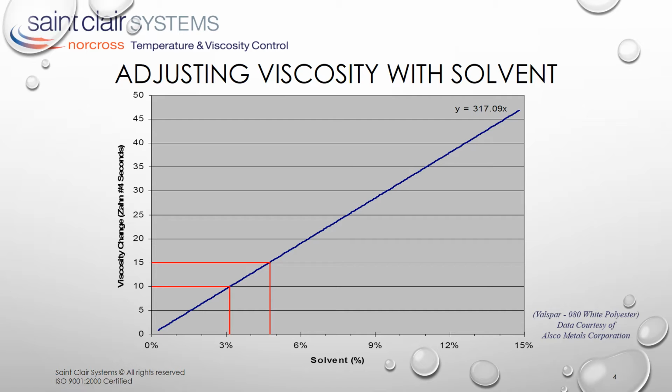To make matters worse, too much solvent can cause issues such as blister, pop, orange peel, low gloss, and even off-color defects. These factors combine to make minimizing solvent addition a worthwhile objective.